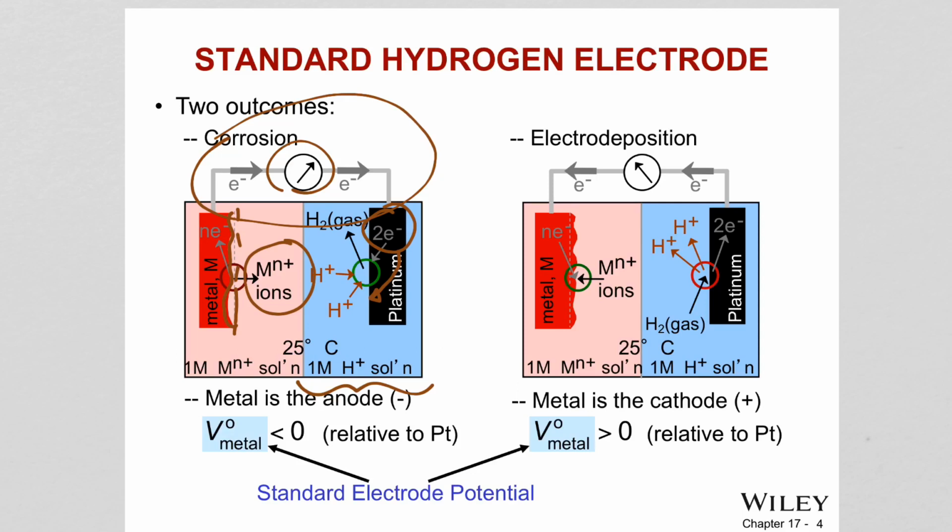So we do this for all types of metals and read that voltage number here and record it basically, and it will give us the EMF series, meaning electromotive force series, which we will use to understand the corrosion tendencies of different metals.